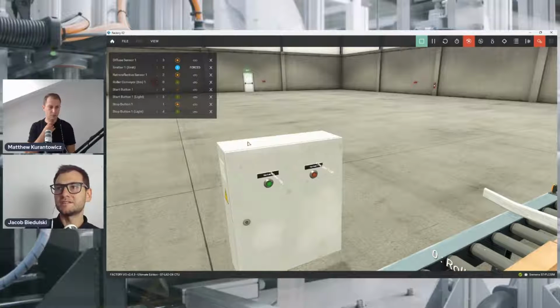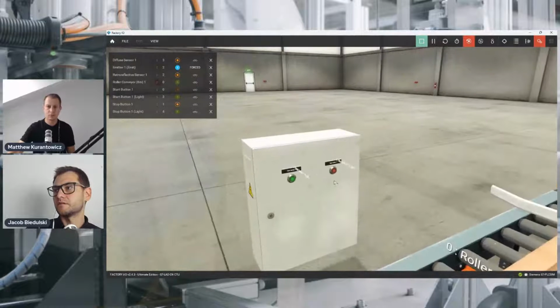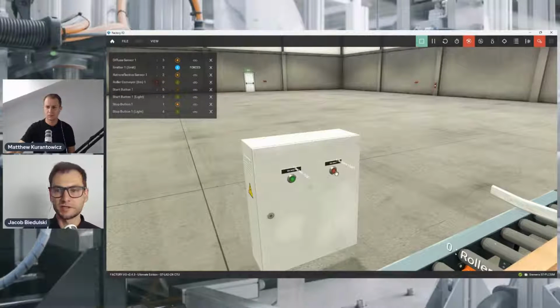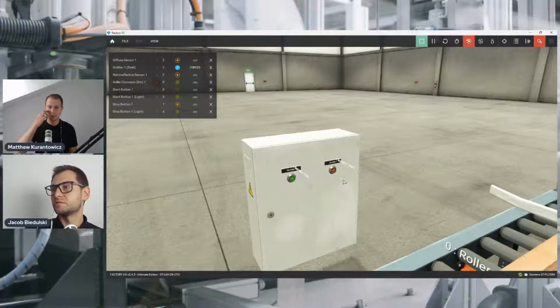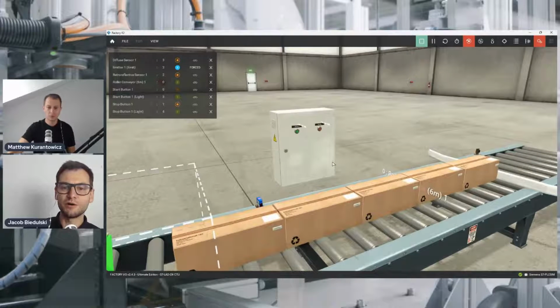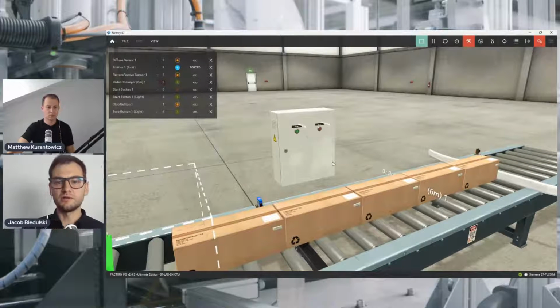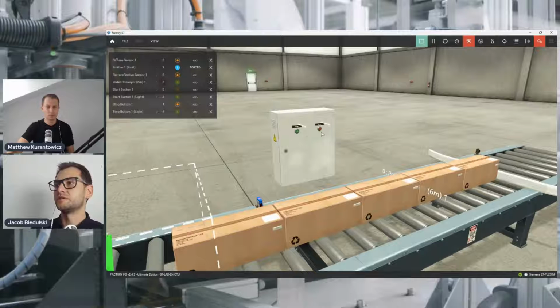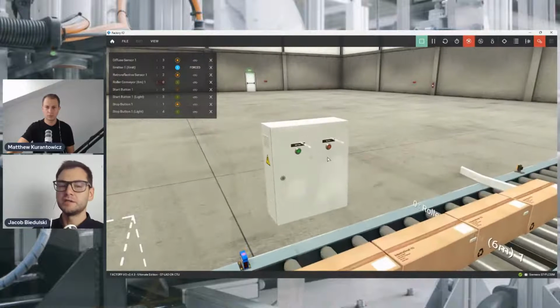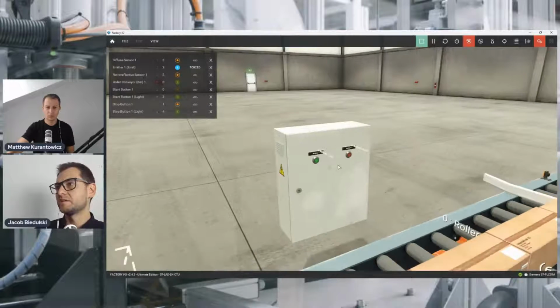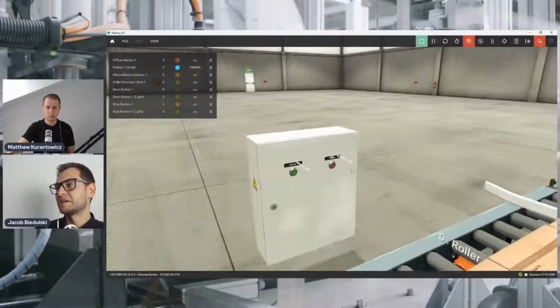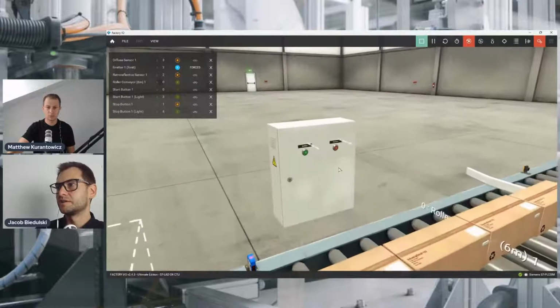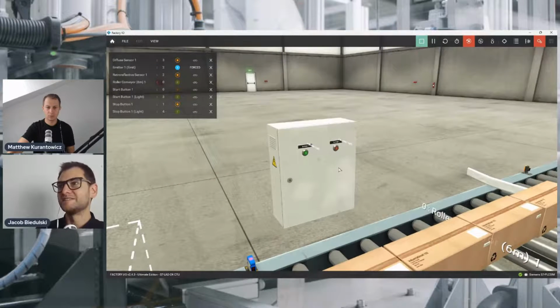Normally closed contacts are used to stop the working state of the machine. Why is that? Because in automation systems, some malfunctions of wiring may occur, for example, and our button or our sensor can be cut off from the system.